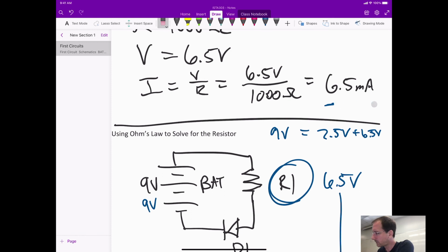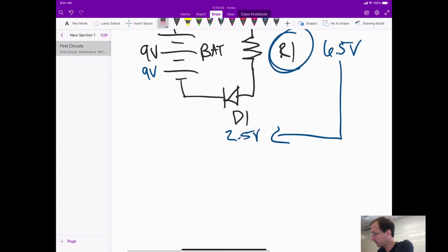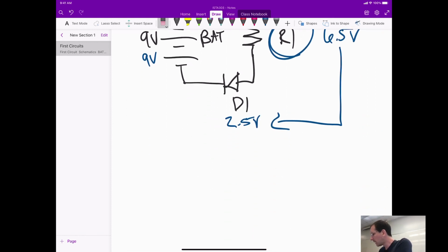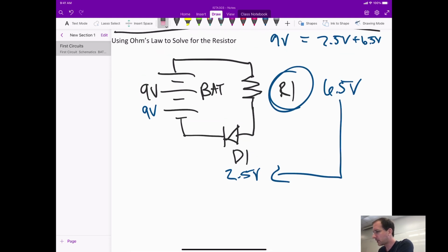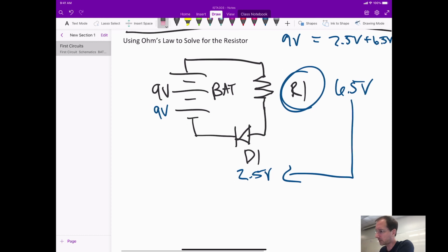So it's going to be some medium amount of light that comes out of the LED. Brightness is proportional to current, and so that's why we care about the value that we set here. So the higher the current, the brighter the LED is going to be. Typically, we want to select the LED current beforehand so that when we're designing a circuit, we have a particular brightness.